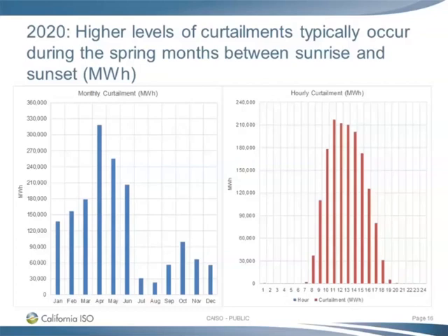Now, a couple of things to keep in mind with this plot. The curtailment is not straightforward. So in other words, we cannot look back and say, this is what we curtailed, and use that as an indication of future curtailments. You've got to be careful. It's like the stock market, you cannot look back and predict a stock's going to move up or down. So here you have a few things that impact the curtailment that are not embedded in the studies. Partly, it's hydro. If you have a good hydro year, under hydro spill conditions, you'd expect to see more curtailments, and vice versa.